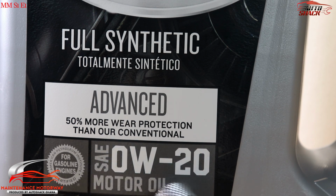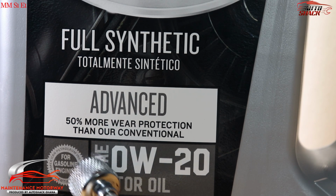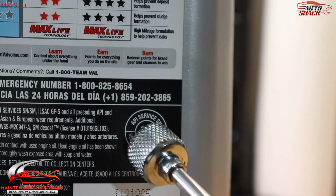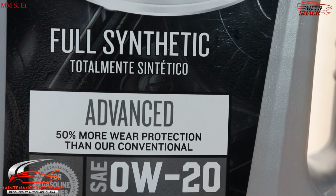So this is extremely important. In a place like Ghana, where we usually have high temperatures, we never actually have winter. It doesn't get as cold as minus 18. I haven't seen that before. So what that means is that if you're meant to run 0W20 and you use your vehicle in Ghana, and you can find good quality SAE 20 oil that has all the standards it needs to have, you can actually run SAE 20 oil because you don't have winter. That's one thing you need to understand.